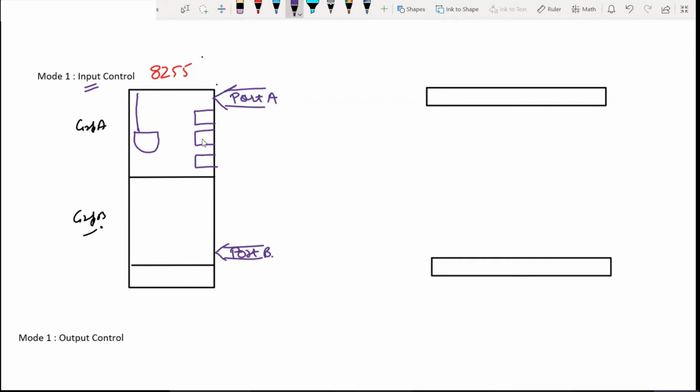Fine. So these three bits that I've just drawn are the bits of port C. What port C bits do we have here? PC3, PC4, not 4, 5. This one is 5 and this one is 4. Fine. So how will these bits be connected? They will be connected like this. They are the inputs of the AND gate. And the output of the AND gate will be connected to PC3. This is the simple connection we have here.